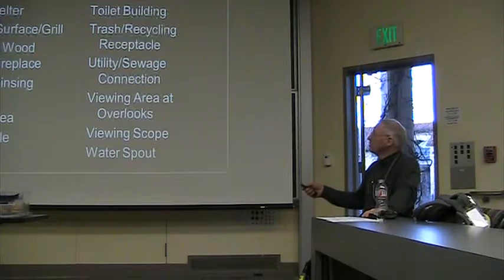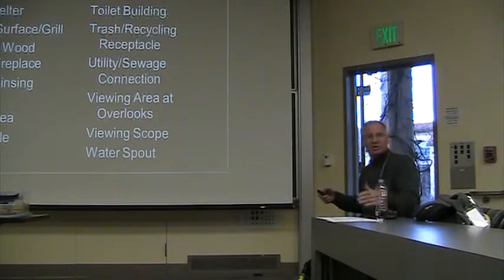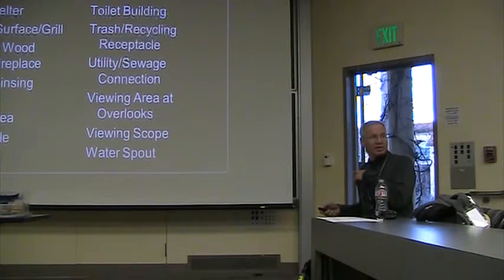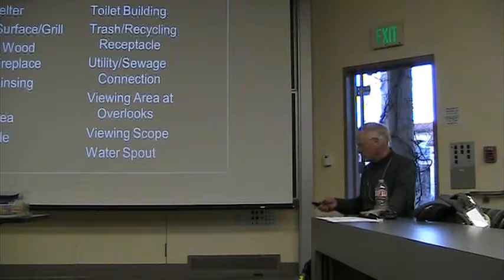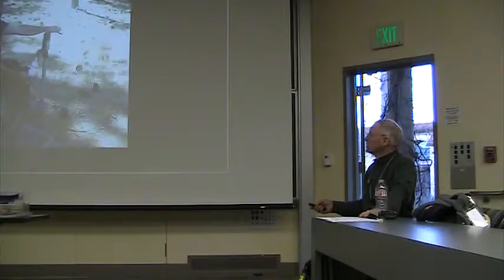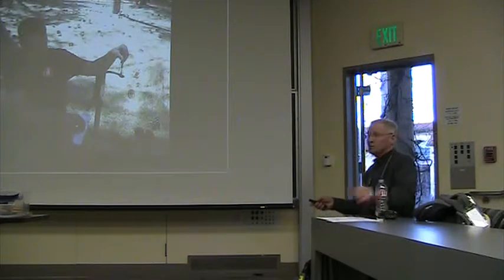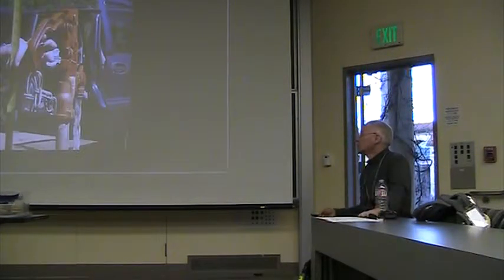And these are all the features that have to be measured for the outdoor recreation process, because there are accessibility standards for each one of these that have now been signed into law as part of the Americans with Disabilities Act. So, for example, a cooking grill has a height requirement, and a water pump has to have certain forces for reaching it and pumping the water. So we measure, with the spring gauge, what the force is.